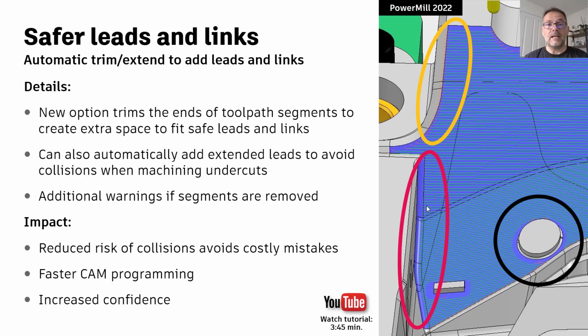Well, in this case, it's because PowerMill calculated the toolpath to machine those purple surfaces, but it allowed the tool to come very, very close to the white surfaces that surround it. And then there was no extra space available to apply the vertical arc move. Because we have gouge checking switched on, PowerMill only has one option, and that is to withdraw the tool vertically.